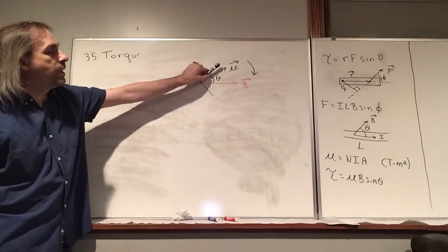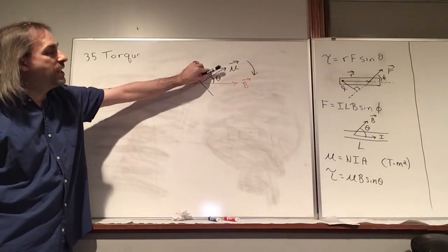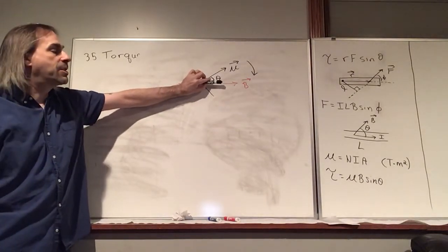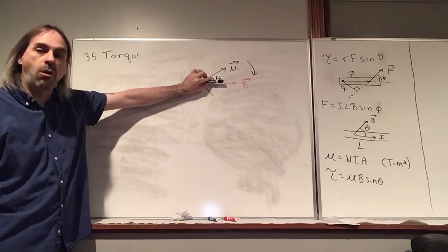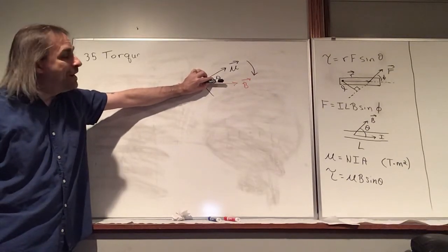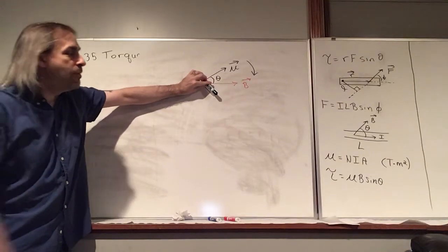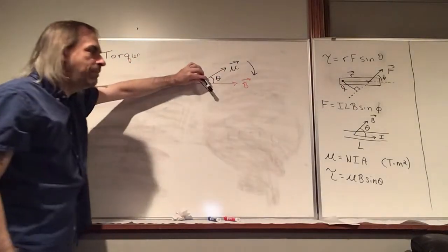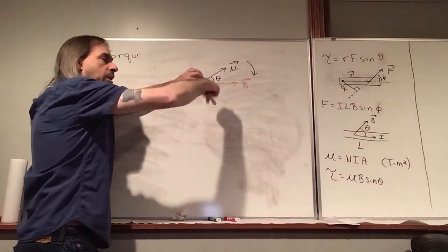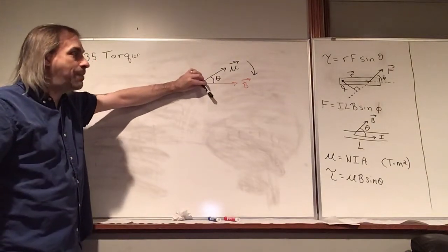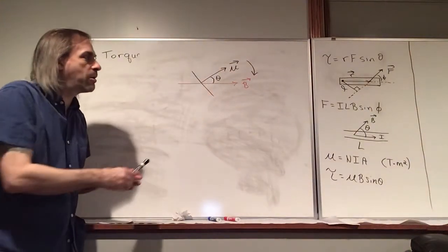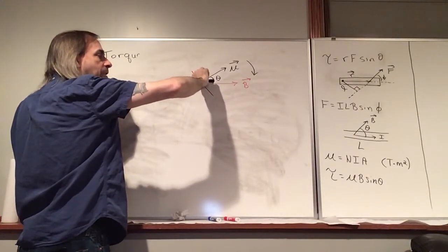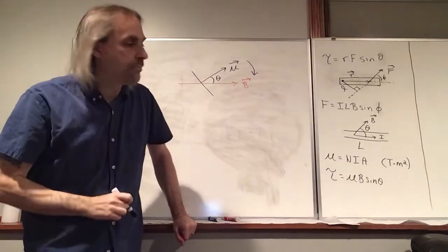Like here, the torque is relatively large, but the torque is decreasing, and then it's going to be 0. Remember, torques cause angular accelerations, so here the angular acceleration is 0. But it'll have angular momentum, so it's going to keep on rotating, and now the torque is trying to spin it the other way. It's still moving this way because of momentum, but the torque is going the opposite sense, so eventually it's going to stop and swing back. So if you were to release this, it would oscillate back and forth, and then eventually settle down and stop because of friction.